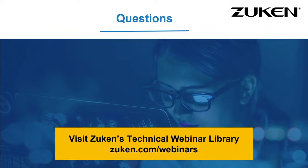Okay, we have another from Paul, and he's asking, I saw in the demo a cross highlight with CATIA in settings. What is that for? Correct. So yes, for this particular version, you do have capabilities of cross highlighting, and what that means is if you bring in a CATIA model within the E3 3D Transformer and you have your CATIA open in the background, anything that you select in E3 3D Transformer will highlight in CATIA. So there's this cross highlight connection between the two tools.